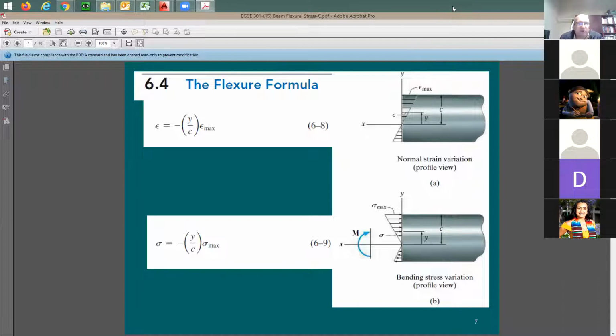We treated the concrete to be homogeneous, which means concrete is able to take tension and compression safely before cracking. Once the concrete starts to crack, performance is going to be completely different. It's going to be a different story. So let's look here at the strain distribution. Usually it's going to be a linear relationship. And this is going to be the neutral axis, right? The neutral axis is going to be somewhere.